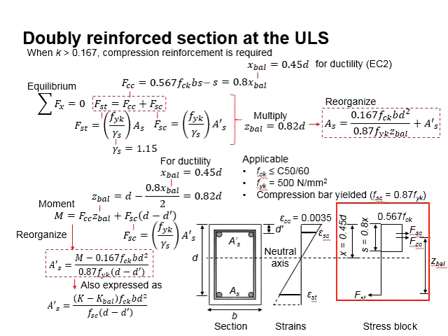The stress plot diagram is also similar to the singly reinforced section, except that there is an additional compressive force from the reinforcement steel embedded in the compressive region. To ensure the tension steel bar yields at the ultimate limit state, the x is limited to be 0.45 times the depth of the section. The height of the stress plot is defined by 0.8 times the height of the neutral axis.